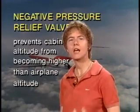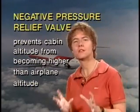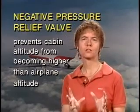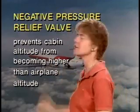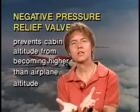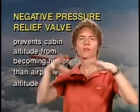Now, a pressurized aircraft is designed to take tension stress, which means stress from the inside of the aircraft pushing out with higher pressure air inside the aircraft than surrounds it. It is not designed to take negative pressure, and so aircraft have a negative pressure relief valve in the pressurization system, and what that does is it prevents the cabin altitude from becoming higher than the actual altitude of the airplane. Another way to put that is it prevents the pressure inside the aircraft cabin from being lower than the ambient atmospheric pressure around it.